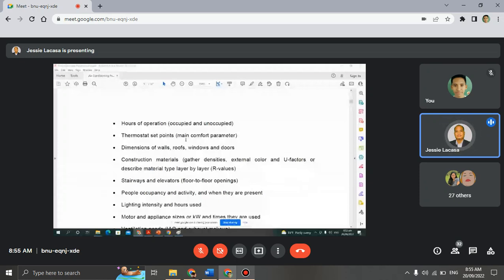12,000 BTU per hour. Okay, so determine design supply air flow rate. Engineers use psychrometrics to translate the knowledge of heating or cooling loads into volume flow rates. The unit we commonly use for the volume flow rate of air is the CFM, or cubic feet per minute, which is the air we need to supply to the duct system.